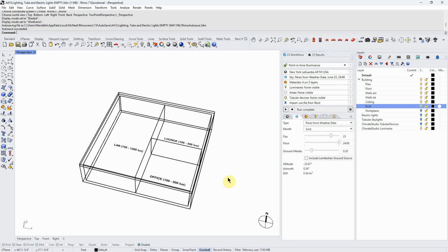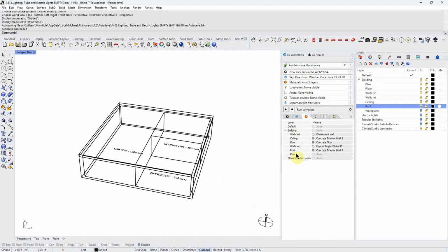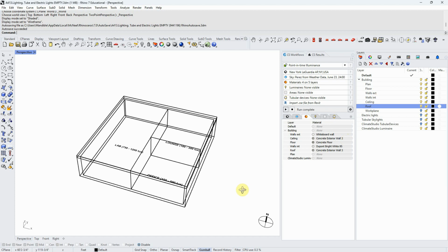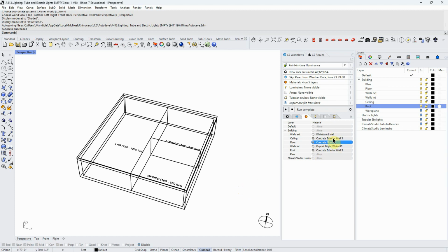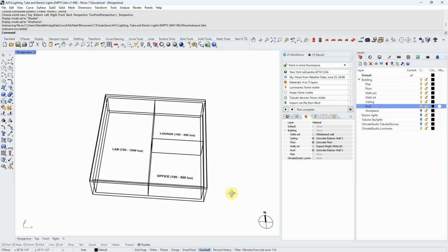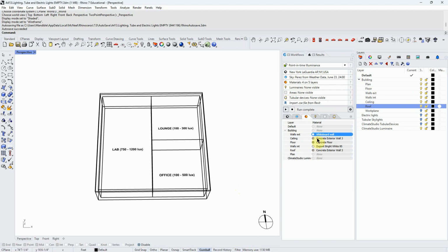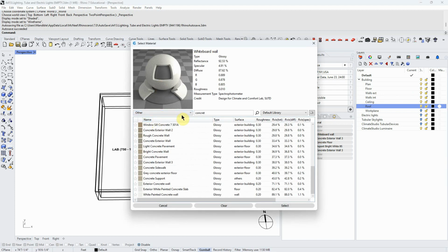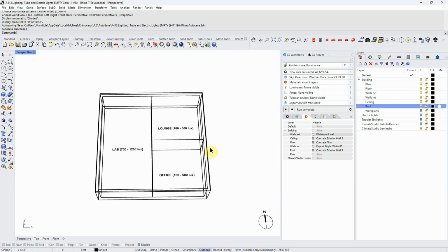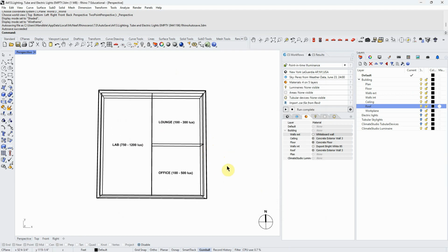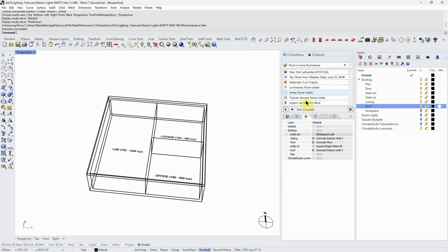So that's what we're going to set it for. You'll remember that in a point-in-time illuminance simulation, we have layers that we want on in the simulation, and we apply materials to them. In this case, there's not going to be any glazing, so they're all solid materials. You'll remember how to do that from other assignments. And now all we need to do is add...